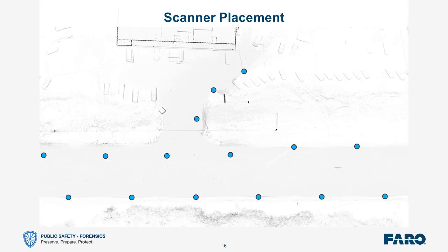That's a really good question, actually, and it's a very common question. The scanner does pick up rain if the color option is turned on during the scan process. In other words, when the scanner makes its second pass and captures photographs at the scanner location, it takes 66 photographs at each scanner location. It will capture water that's coming down, if it's coming down hard enough, and it will continue to capture water that may have landed on the prism of the scanner.